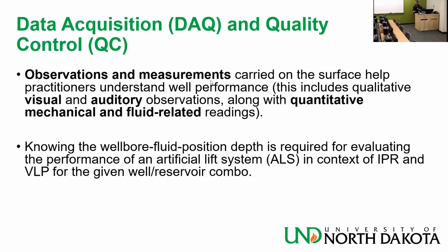Knowing the wellbore fluid position depth is required for evaluating the performance of an artificial lift system in context of IPR and VLP for a given well reservoir combo. So remember, well deliverability is a dynamic analysis between reservoir and well. What can the reservoir provide? What can the well facilitate? What flow can the well facilitate?